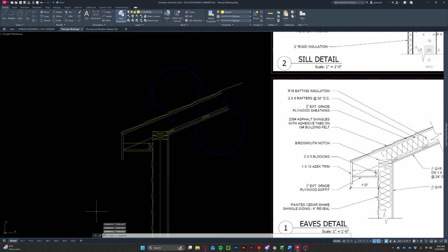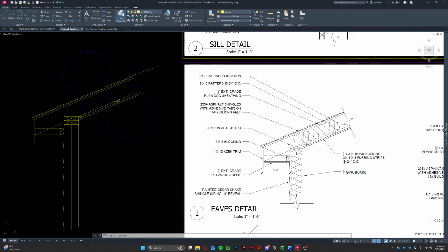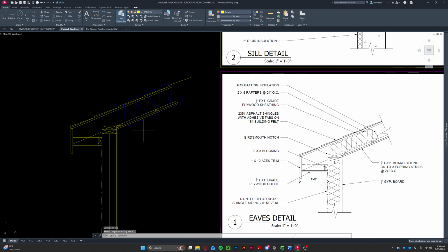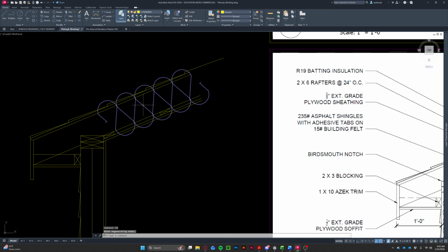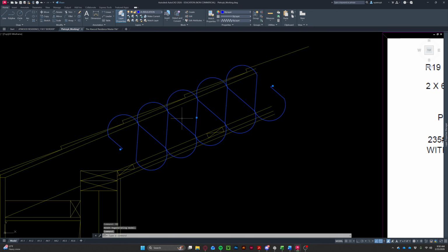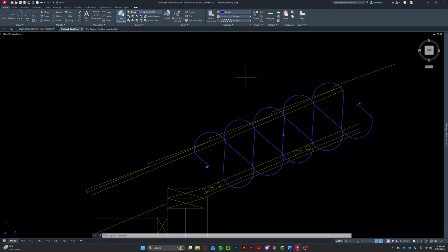Now, this may look absolutely massive, and that's because it kind of is. Just note that this is going to get printed at 1 inch equals a foot size. So I'm going to change my viewport to be 1 inch as a foot. And even then, when I do a regenerate, this is still really big. So I'm going to take this and go to the properties manager. We went over it in this class before, I think last week.